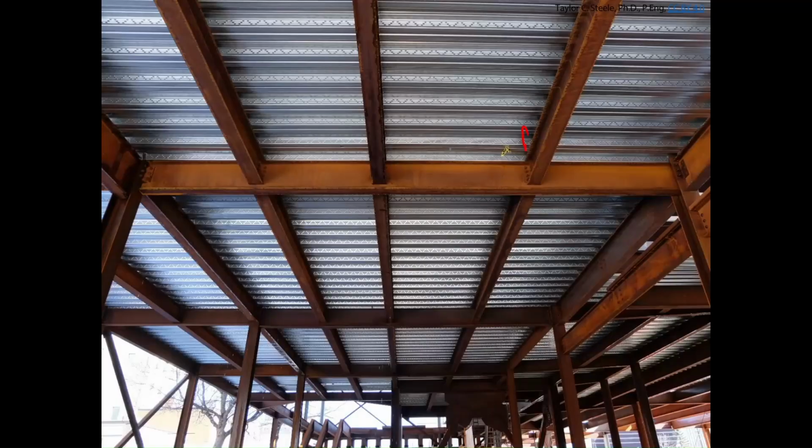We'll remember that joists basically carry a uniformly distributed load on them. Those uniformly distributed loads turn into reactions at the connections. Those reactions are forces on the girders. And because the joists are attached to the steel deck, normally there's some kind of fastener from the steel deck to the top of the joist. That's going to stop the beam from wanting to twist sideways, and so we're going to focus on calculating the strength of beams in that kind of situation today.